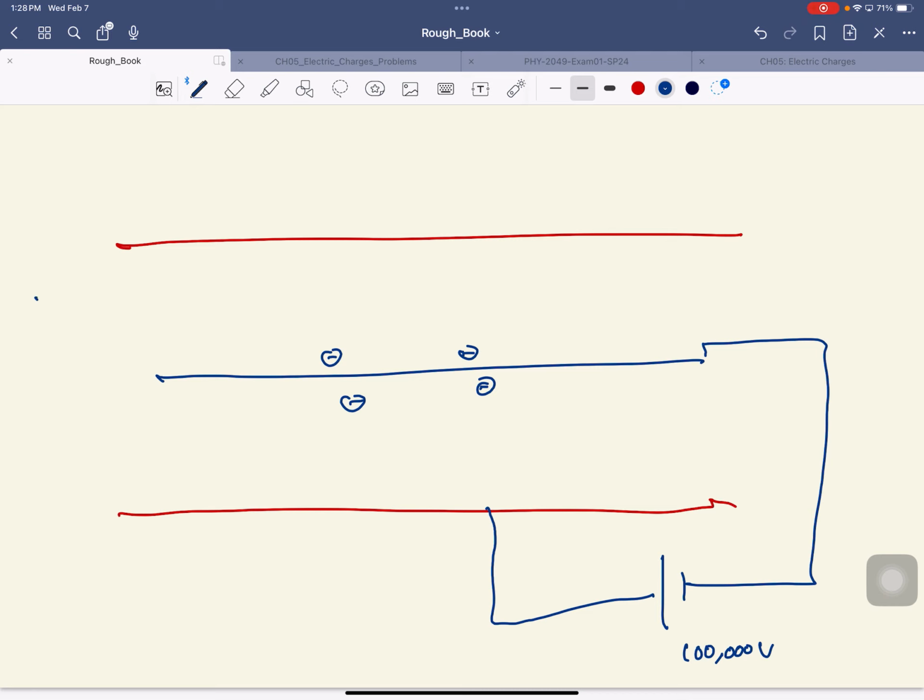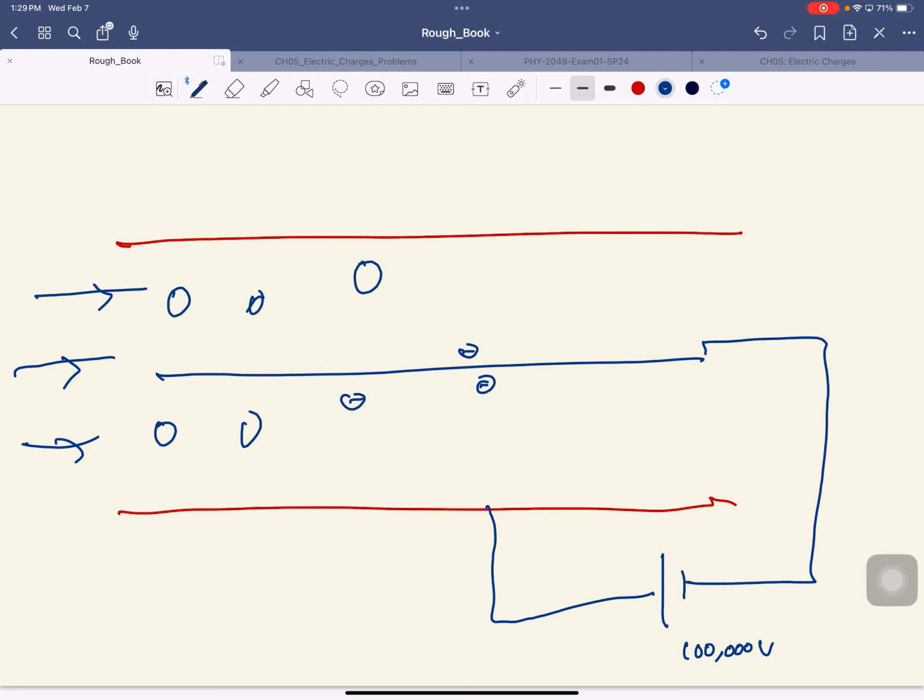Okay. Now let's say the smoke-filled air is sent here. Here are the smoke particles. They're fairly large. And then what will happen is, as the smoke particles are traveling, these negative charges, electrons, will stick to the smoke particles. What are these plates? They're connected to the positive terminal, so they're positively charged. What happens? These smoke particles come and stick there.